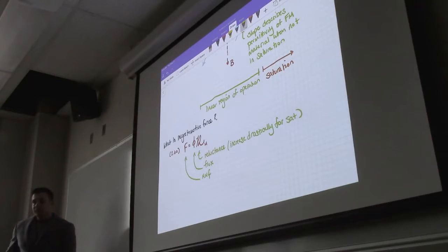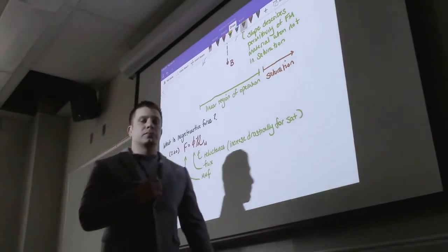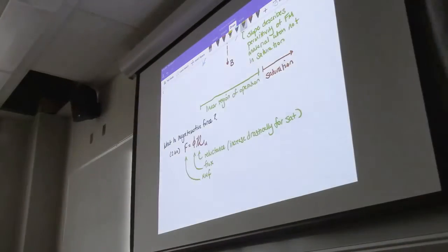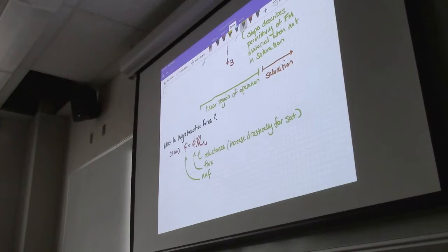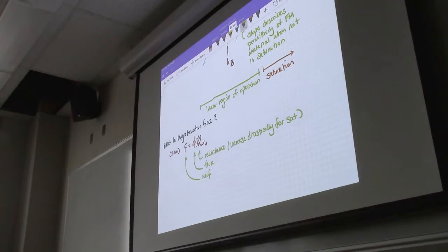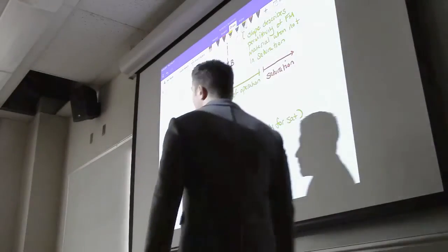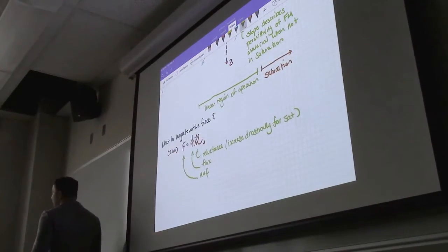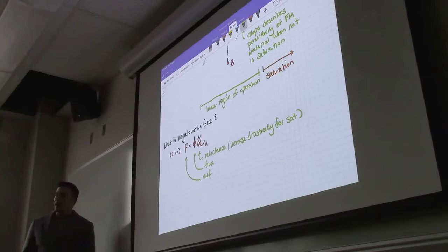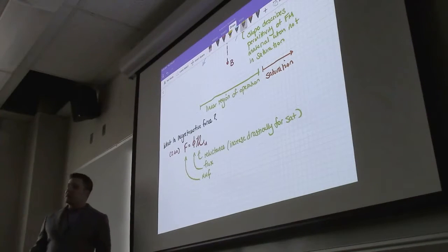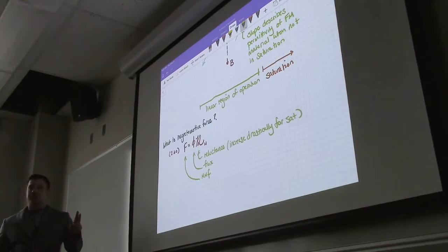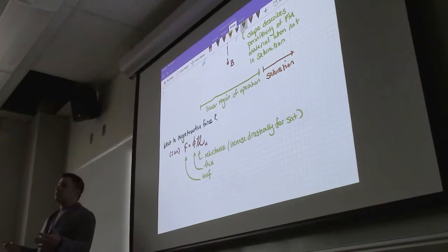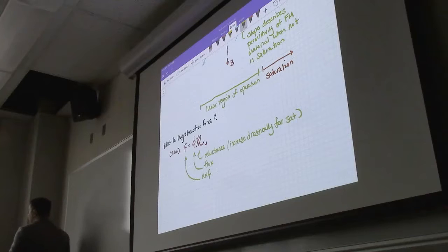The reluctance is equivalent, quote unquote, to resistance for the magnetic field, and so you can see sort of a V equals IR type of relationship being set up, right? Where the MMF would be the voltage, the reluctance would be the resistance, and the flux would represent the current, which is the amount of magnetic energy that's flowing through the circuit.